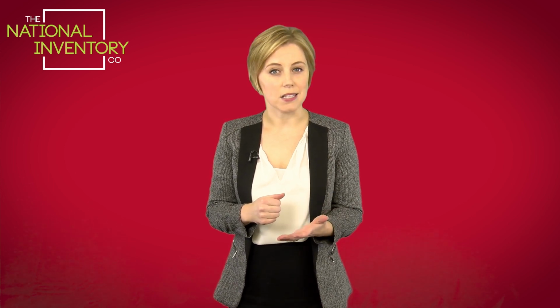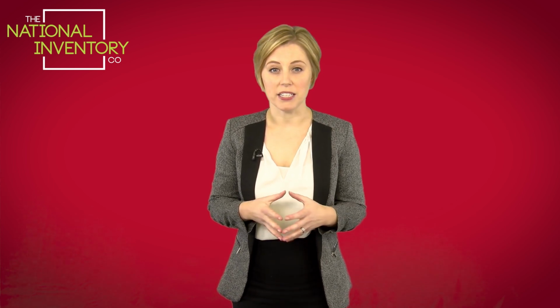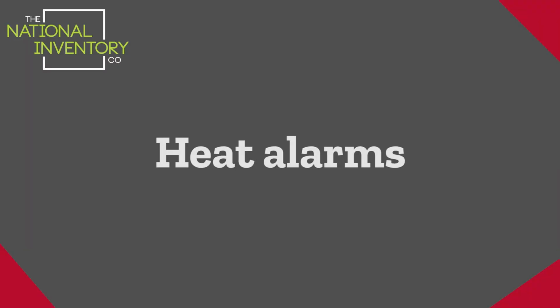Please remember, a smoke alarm is designed to respond to a smoke test. In the event it doesn't respond to smoke, it indicates that the alarm has failed and a new one should be fitted. The majority of smoke alarms now come with an expiry date. Hardwired smoke alarms have a 10-year lifespan and battery-operated smoke alarms have roughly 7 years, but please refer to the manufacturer's guide. You are legally required to have a smoke alarm on every habitable floor of a rental property.